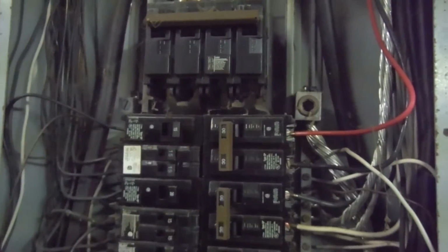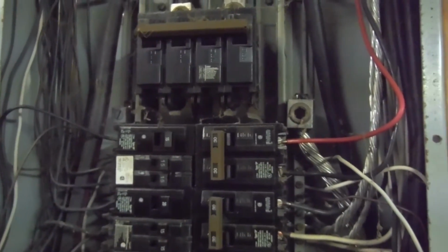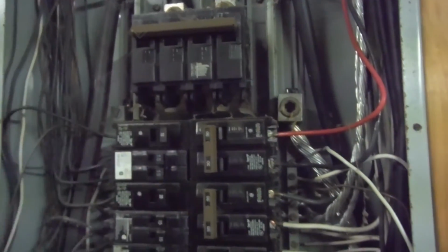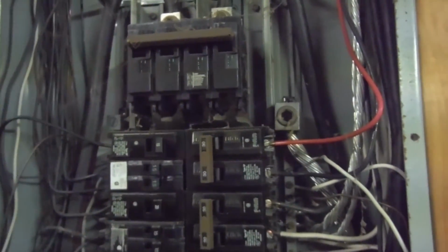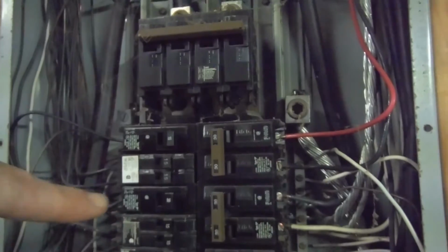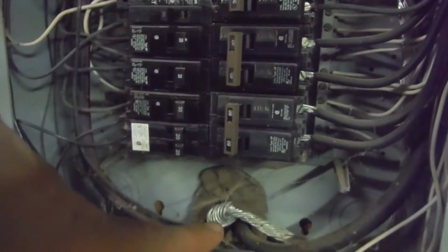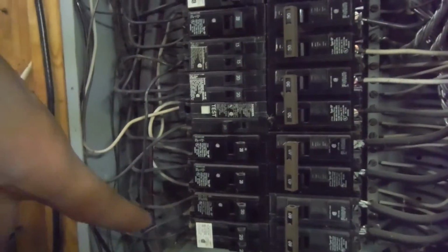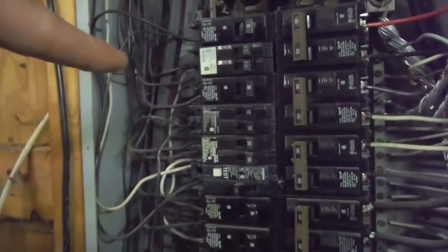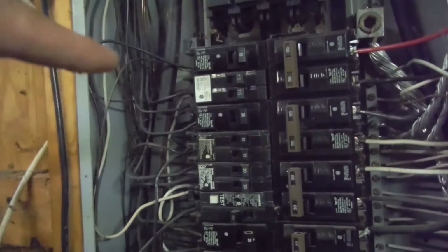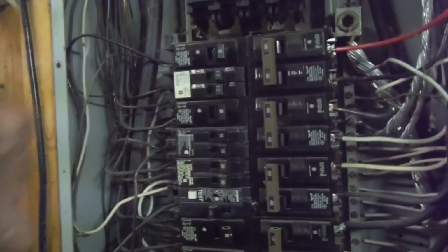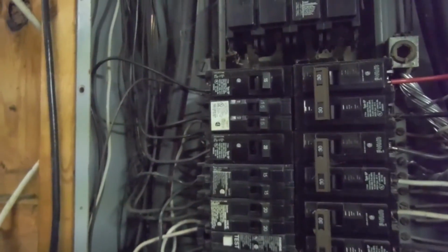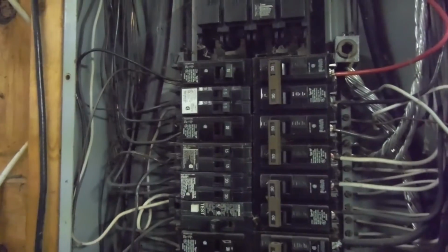I mean, 120 in, 120 in, and your common, or I guess in this sense, is really your ground. Newer applications will actually have this as well as a white line coming in from the street, and it will come in usually on the opposite side, and it'll have its own bar not connected to anything, and all of your neutrals will be plugged into there. But alright, let's go back to the makeshift circuits and talk about how a normal circuit is really run in the house.